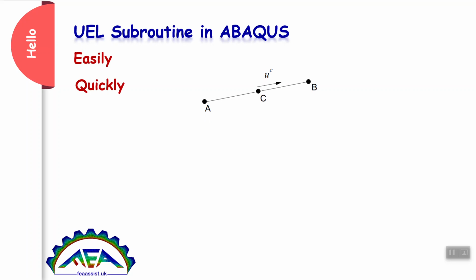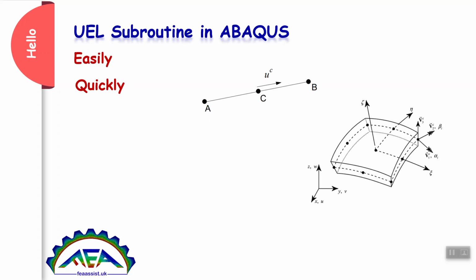Interpolation function can be linear or cubic. You need to define your function in UEL subroutine. For 2 and 3 dimensional problems, it's the same. We need to define a new element with a new interpolation function. To understand these things well, stay with us.